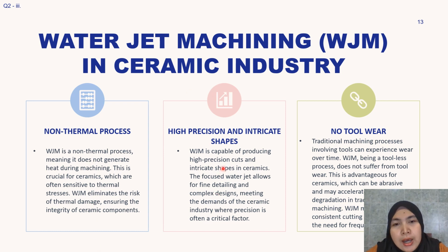The second one is high precision and intricate shapes. Water jet machining is capable of producing high precision cuts, allowing for complex designs in the ceramic, meeting the demands of the ceramic industry where precision is often the critical factor. And the last is no tool wear, because water jet machining is a toolless process, so it will not suffer from any tool wear.